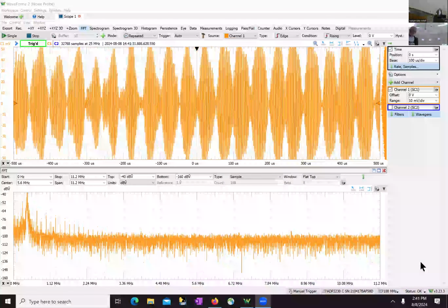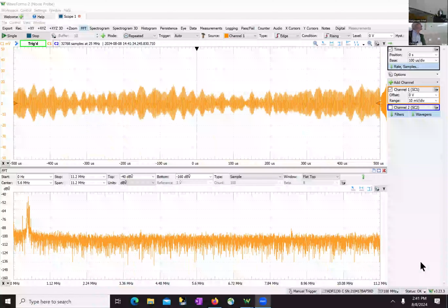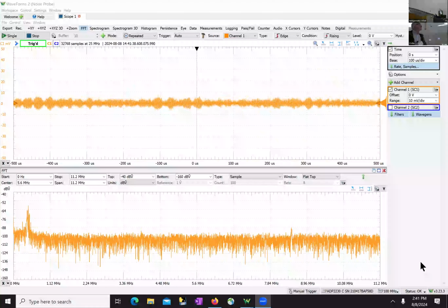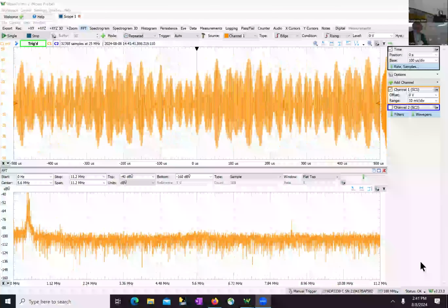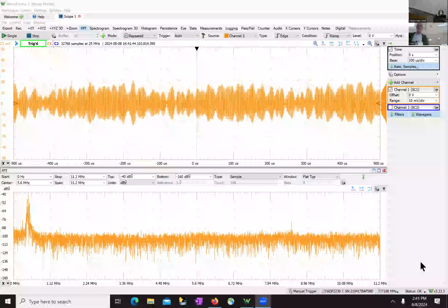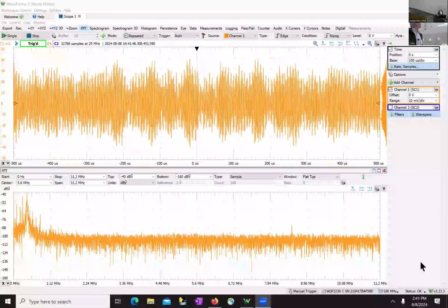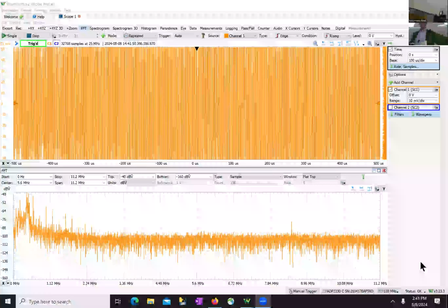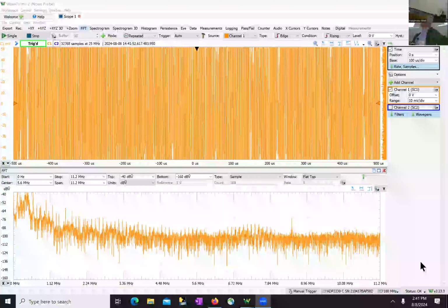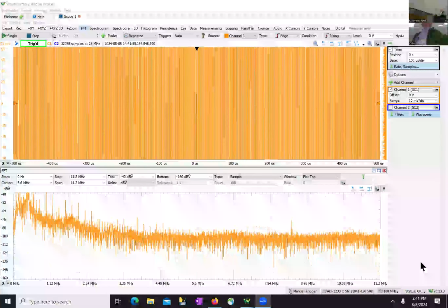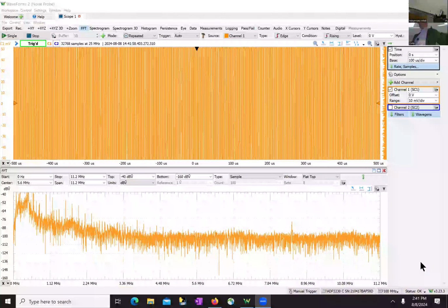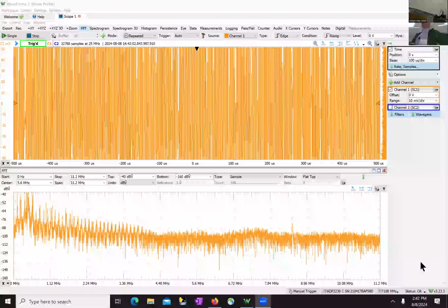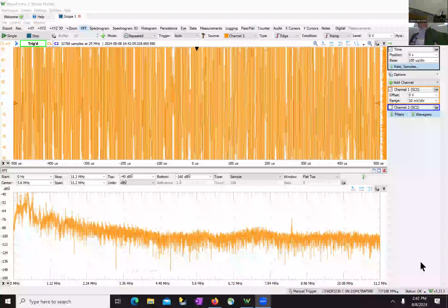Things that are noise sources are keyboards. Keyboard's not so bad today. Mice. So that's your mouse. There's some noise from your mouse. Power supplies are just terrible. I think I have here the power supply for the laptop. Oh, telephone, sometimes you can't. This isn't set up for that high a frequency, but yes, your cell phone is emitting RF signals.